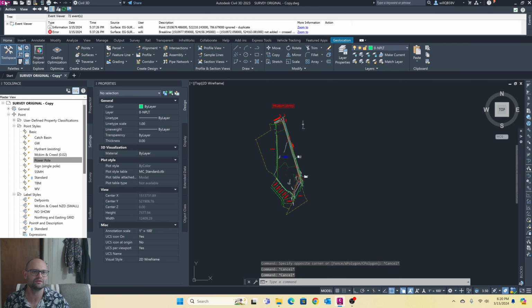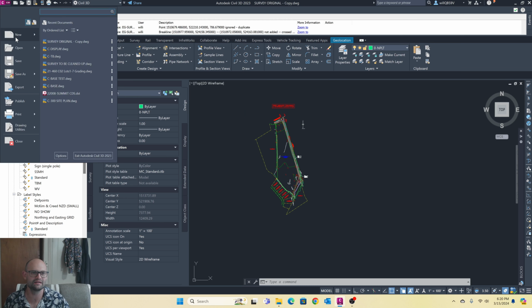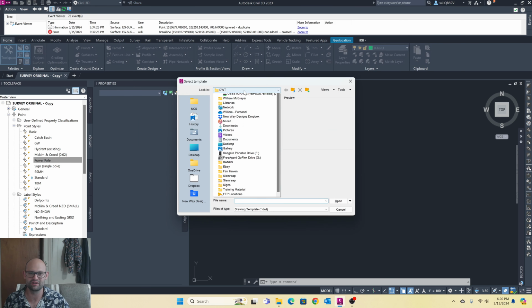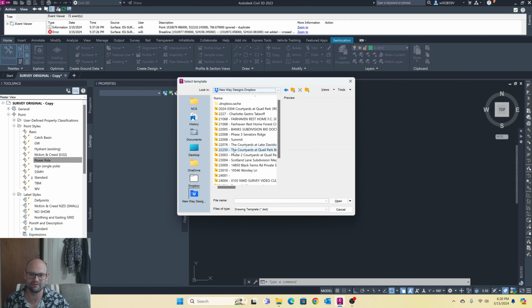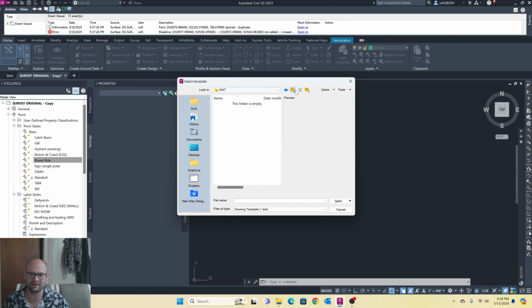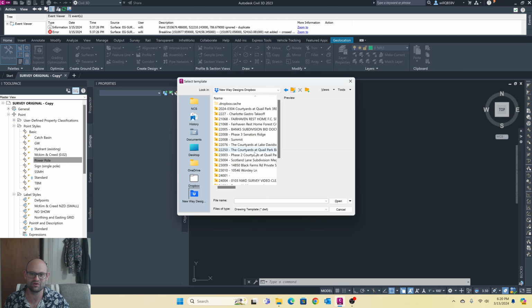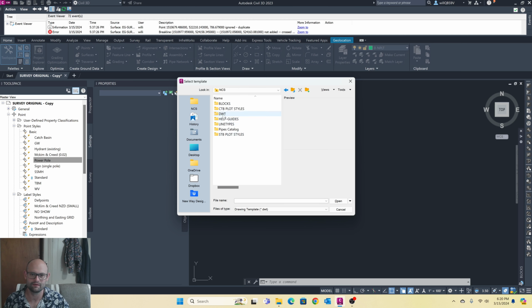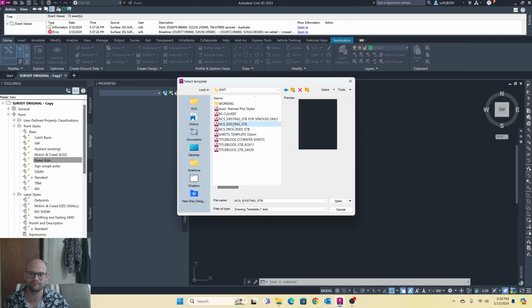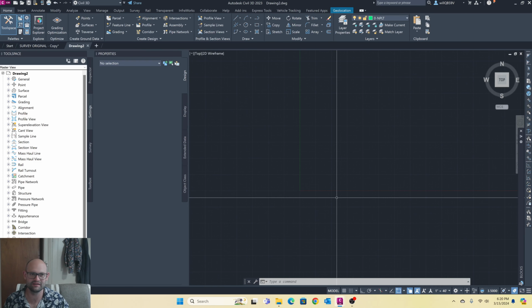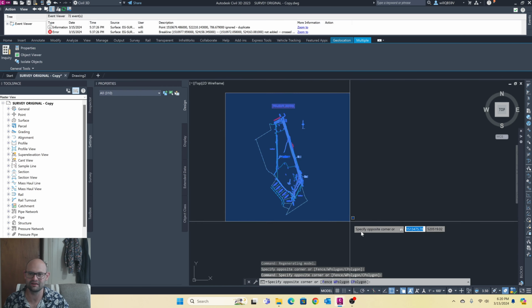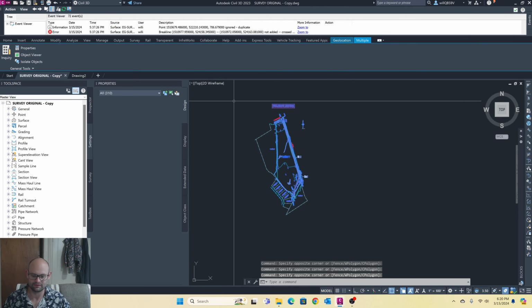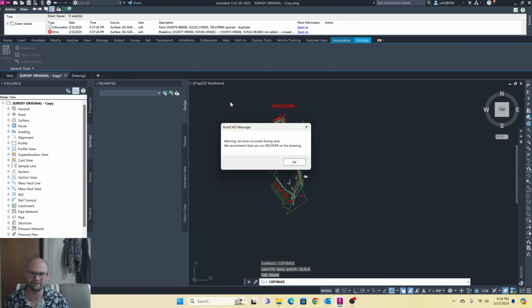And what I'm going to do is I'm going to hit the Civil3D icon over here, hit new. That's going to bring up my template options. Again, we're going to dip to the Dropbox because that's more up to date than what I have stored on my local bit here. DWT, bringing it to the existing, open that up. And all I'm gonna do is take this, select everything in it, go both ways. Type in COPYBASE 0, 0, 0.